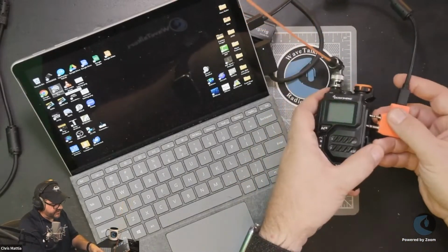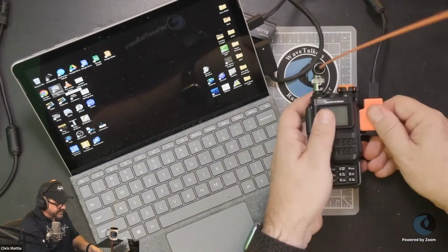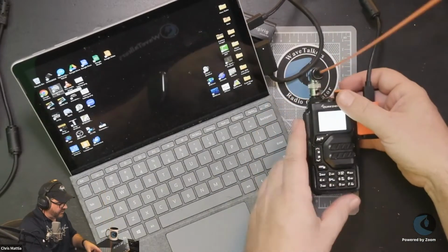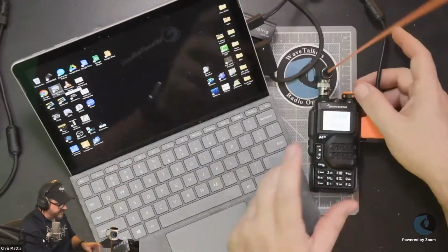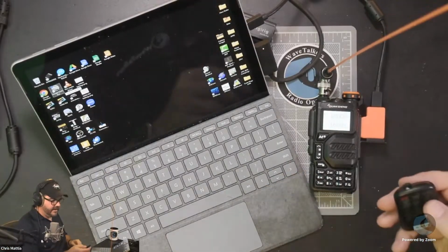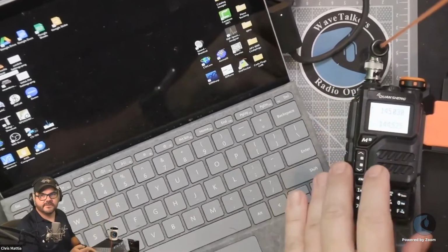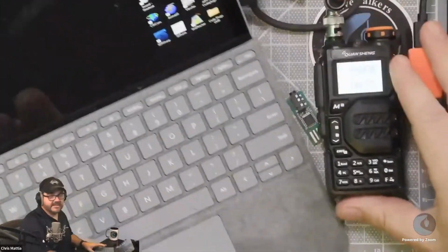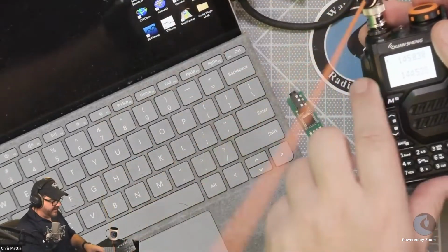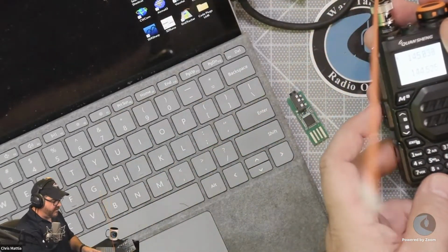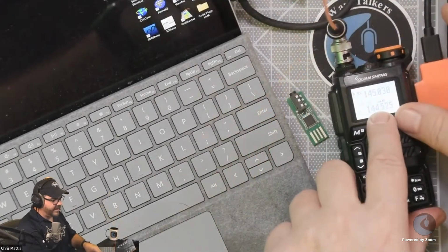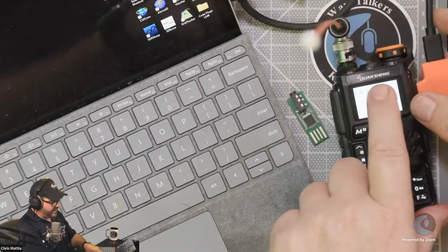So when I plug this into the side of the radio, just make sure it fully seats into the radio. I've got my 90-degree BNC connector here, and I'm just going to go ahead and turn on the radio. I mentioned that there are sometimes some settings that you need to make. Let me zoom in a little tighter on this setup so you might be able to see things a little bit better. The display is going to be a little bit hard to read here. But on the display, I'm not seeing any audio levels coming in. So I'm going to press, there are 3 buttons here on the side, the middle button, and you'll see that there is a little levels indicator. That just indicated that I'm now bringing audio in at this point.